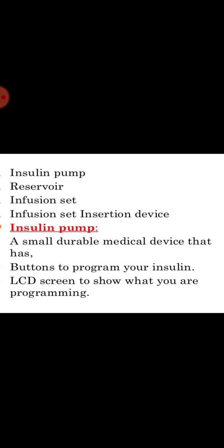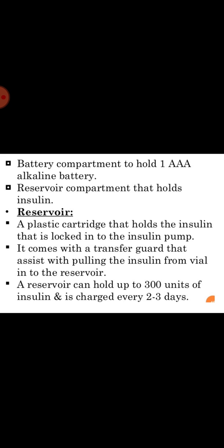The insulin reservoir consists of a collapsible laminated foil bag and forms a one-trip part together with the attached silicone pump tubing. The catheter can be connected to the pump tubing with a standard Luer connector. A number of alarm and safety circuits ensure that a dangerous condition cannot occur. In the case of failure of a system component which would lead to unintentional overdosing, the pump is automatically switched off and an acoustical signal is triggered.